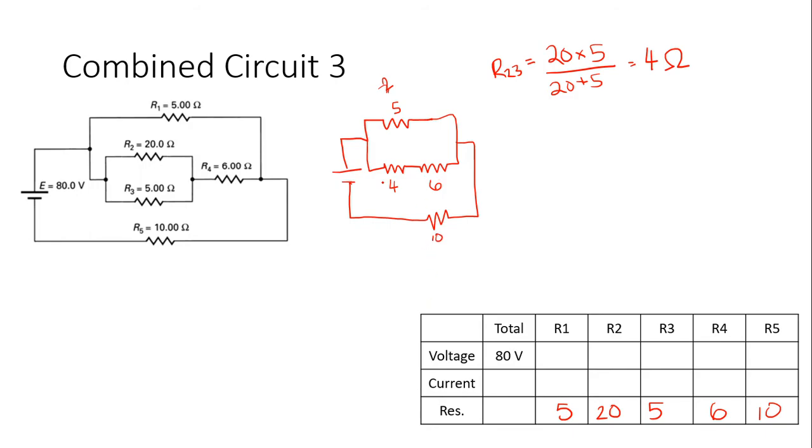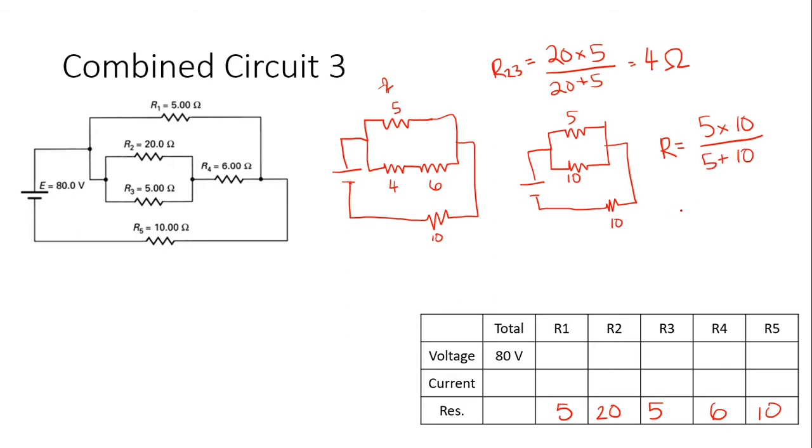So, next step, you've got 2 in series, simplify it. So simplify, simplify. Leave the 5. This is going to be added together, and you have your little 10 floating down here still. Okay, 5, 10, 10. Here, same trick. The resistance of that is equal to 5 times 10 divided by 5 plus 10. So your resistance is going to be 3.3 ohms.